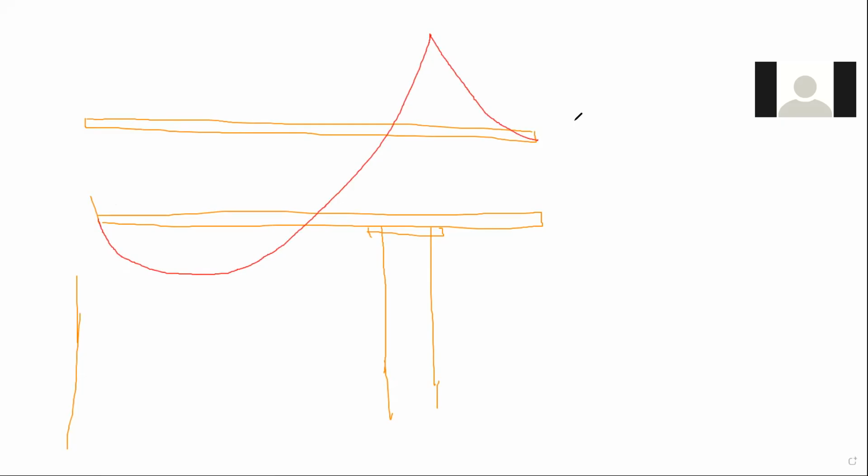Now for every load case that we have, they basically have the same pattern, not the same value, but the same pattern. Do you follow that? Now this represents a positive moment, this represents a negative moment. But there's no such thing as positive moments and negative moments. All this means is that positive means bottom is in tension, top is in compression.